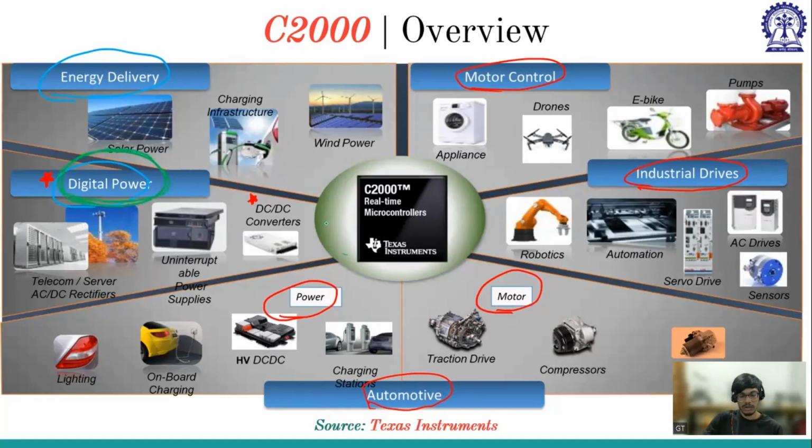You can go to the TI website and see what all microcontrollers they have made specifically for DC-DC converters. It will give the set of families, similarly to STM, where it has 4 such families, and we have narrowed down to the microcontroller optimized for mixed signal application. Similarly, you have to see which family of this microcontroller is suitable for DC-DC converters.